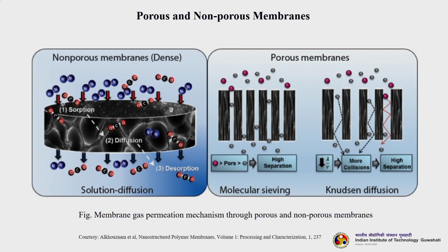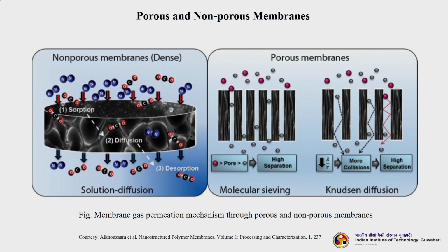We have heard about solution diffusion in a few of our classes and I explained it in a nutshell also. Today again I am telling that. The meaning of solution diffusion is essentially that two factors play a big role. One is the solubility and the other is the diffusivity of the solutes that we want to transport across the membrane.